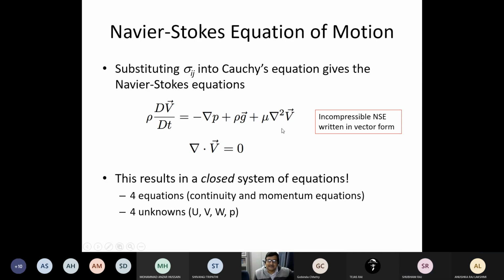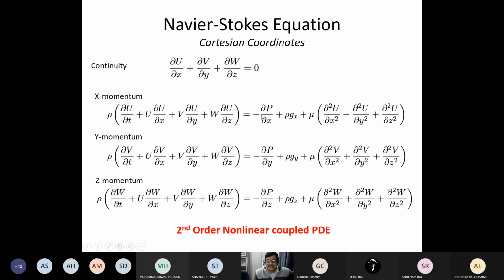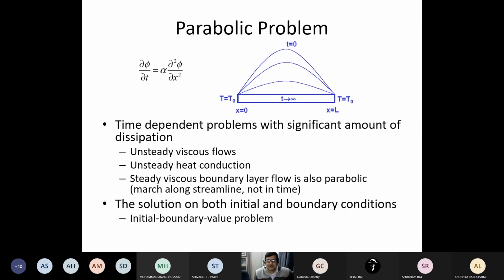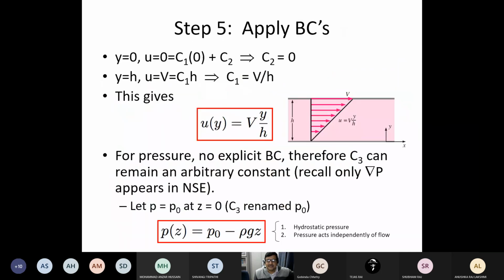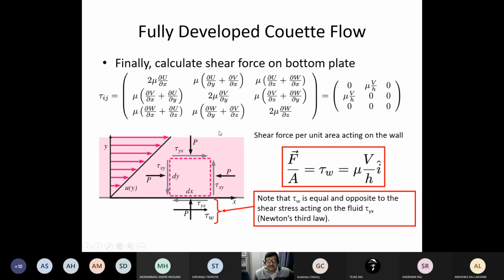How come you get this? When you try to get this, what do you assume? You assume Newton's law of viscosity, which is like this. In this, you say that this is equal to this, right? Moment you take these to be equal, you enforce that there is a balance of angular momentum too. If these two are not symmetric, then there is a chance that the angular momentum has not been considered.